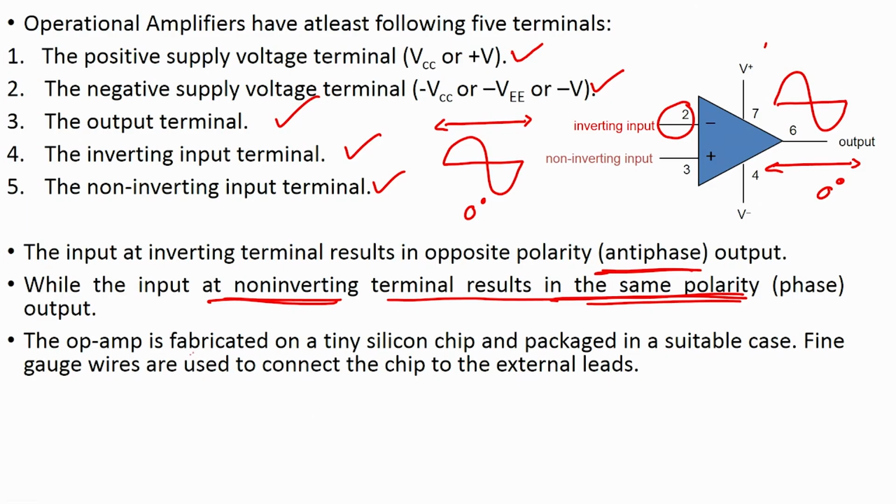So, now we understand that if I apply input at inverting, output will be out of phase. If I apply signal at non-inverting, output will be in phase.